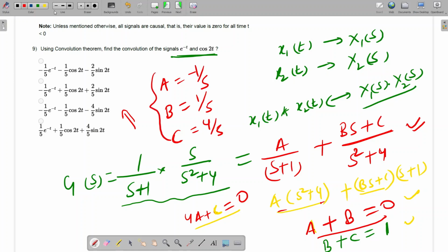See, one thing is written here: causal. Causal means, where are our poles? All the poles, if we see, are at 1 and minus 1. And here this is an undamped system, so plus minus 2j. So sigma here should be greater than something. Everywhere we use the normal rule, step 1, so sigma should be greater than minus 1. So the normal rule we have to apply. It is causal only.